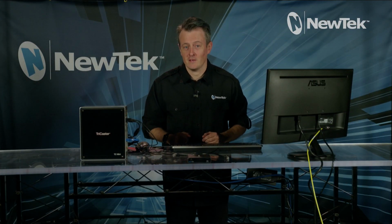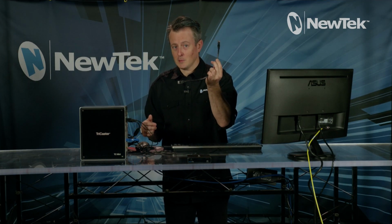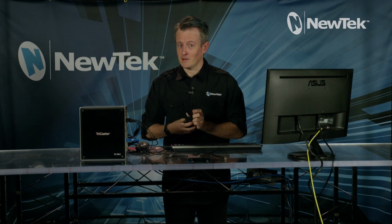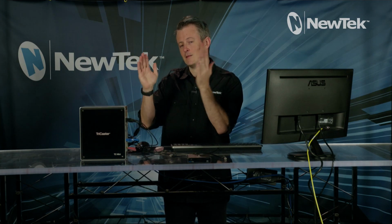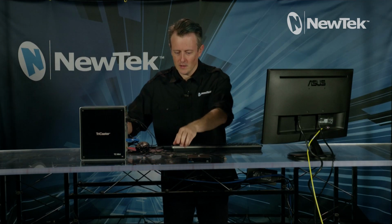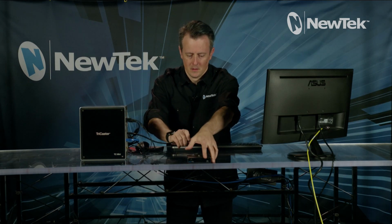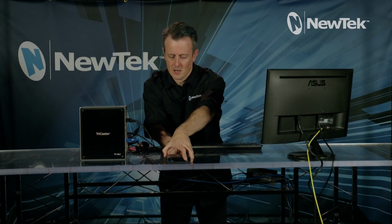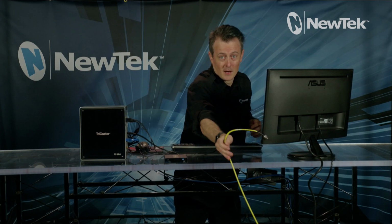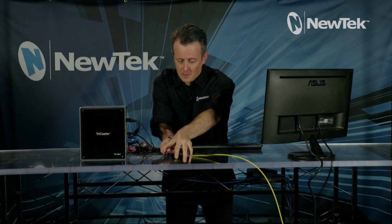To connect the 12G SDI Spark Plus IO, you'll just need the unit itself, an Ethernet cable to connect it to your network, an optional power supply, but for today's example, we're not going to need that because we're going to connect it directly into the TriCaster Mini 4K, which has PoE connections on it. So let's go ahead and plug that in first. I'll plug it into the Ethernet jack on the back. And then I have the camera that is currently pointing at me, a 12G SDI signal right here, which I will connect into the input of that system.